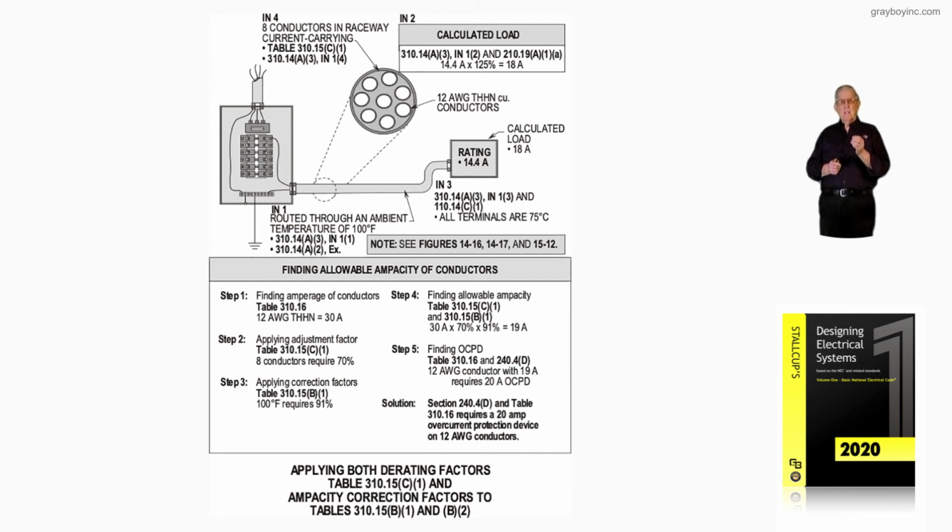So in the application then of the 2 tables in step 2, we take 75 amps for this conductor, number 6 THHN, from the 90-degree column of Table 310.16, and then we apply the correction, we take 87% times 75 amps, we come up with 52 amps. 52 amps is greater than 40 amps, as you see in the calculated procedure.